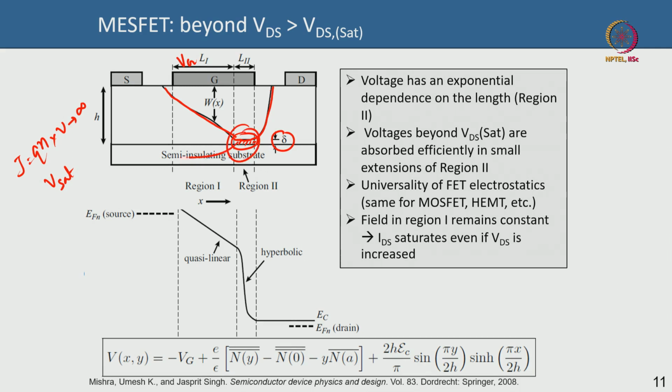At this critical point the electrons locally travel at the saturation velocity, but not throughout the channel. Which means the current density you will get is limited, and so is the thickness of the opening. This opening cannot become arbitrarily small, because the current continuity has to be maintained.